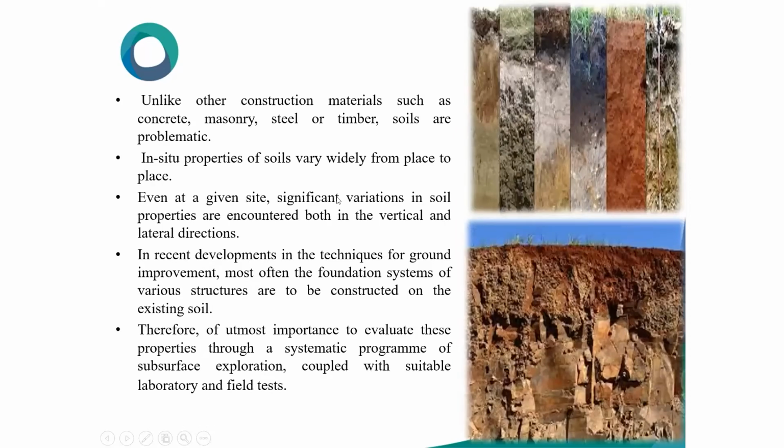Next, in this module you will try to understand why you want to do soil boring and why you want to learn different stratification. When you are doing the boring, you will see different layers of soil. You can see the color.